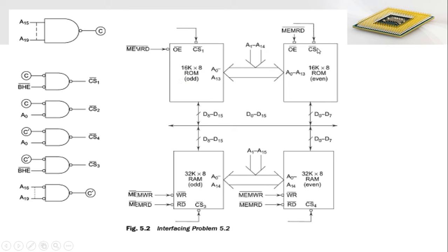And for ROM memory, the processor can read data from memory. The read operation is only possible with ROM type memory. So the processor needs to generate the memory read control signal, which is connected with the output enable pin of ROM. So this output enable pin of ROM is always connected with the memory read signal generated from our processor.